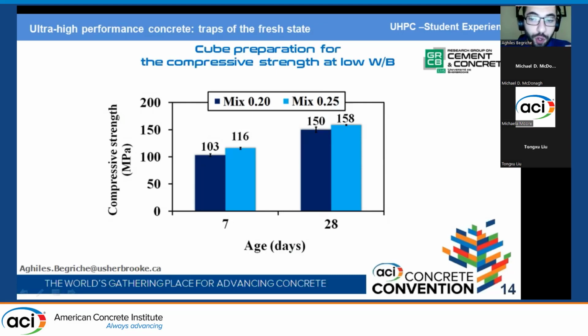So we recommend to break the thin crust at the top of the sample during the vibration to eliminate to the maximum the excess of entrapped air during the molding of the sample.